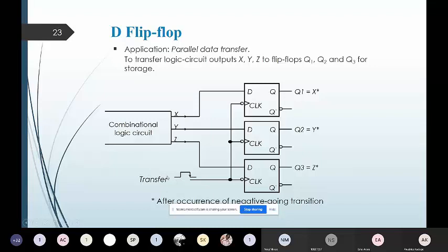And if you are observing, for this clock edge, the mark has been given, which is the downwards mark, and from that downwards mark, you have to understand that these D flip-flops are the negative going transition based D flip-flops. And that's how here you can get the discrimination to be done in the operation of positive edge triggered base or negative edge triggered base flip-flop parameters.